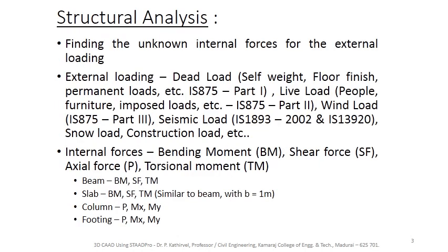Structural analysis is the process of finding the unknown internal forces due to the external load applied. The external loads are mainly due to dead load, which includes the self-weight, floor finish, permanent loads, etc., as specified by IS 875 Part 1, and then live load, which includes the people, furniture, imposed load, etc., as mentioned in IS 875 Part 2. So both these dead load and live load are gravity loads, which act vertically downwards.